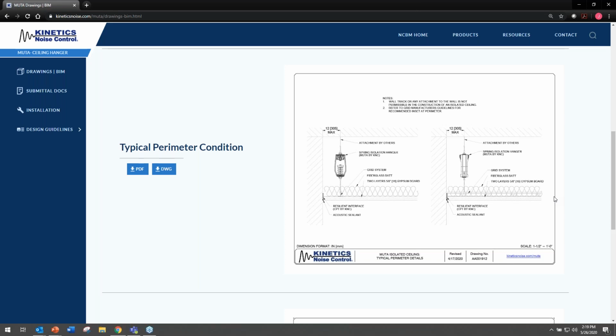Whenever I get asked about cost, I always go back to say, especially with ceiling hangers, the shape of that ceiling has so much to do with the cost. If you have a giant rectangle, you are going to get roughly 12, 13, maybe even 14 square feet per hanger when it's all said and done. But if you have a ceiling layout that has all kinds of crooks and corners and they want to do the closets on the project, the lowest I've ever seen is 9 square feet per hanger. Obviously, there's going to be a giant difference in how much that overall project costs based on the shape of that ceiling.